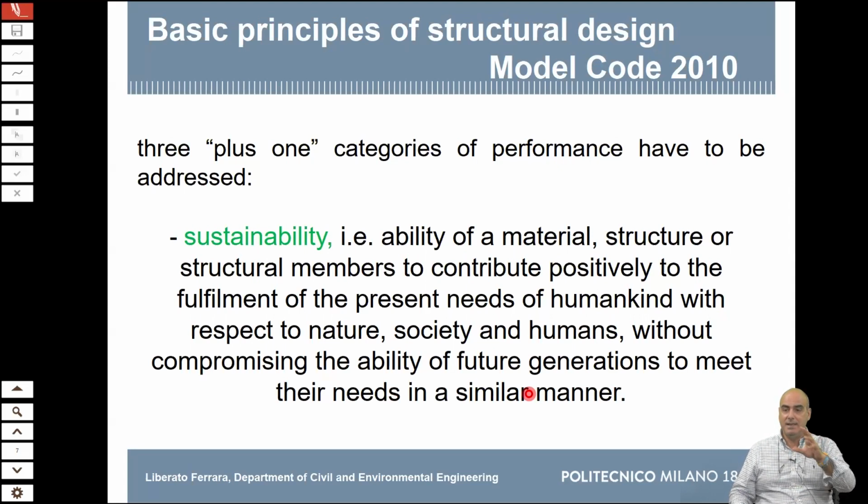So it was around a 60% reduction of the material. Very, very effective. But then we realized that some of the constituents, silica fume and the fibers, have to come from very far away. So the impact of the transport jeopardized half of the sustainability benefits. This is something that we must not forget.